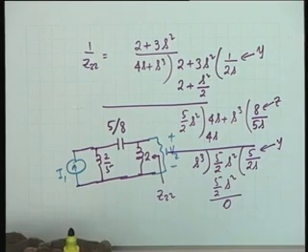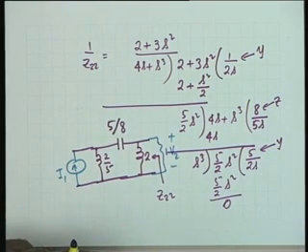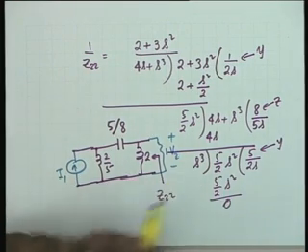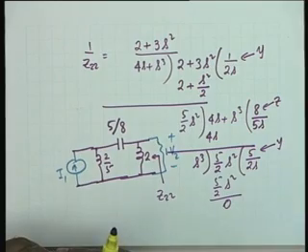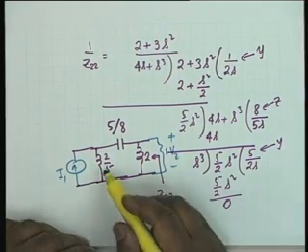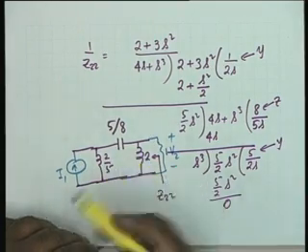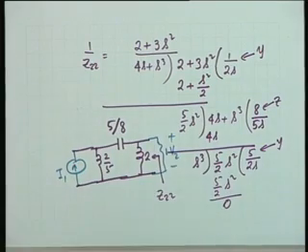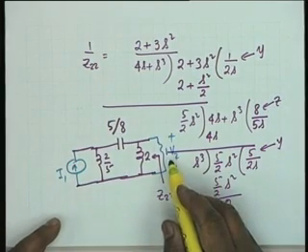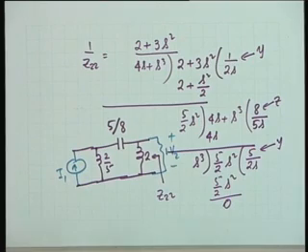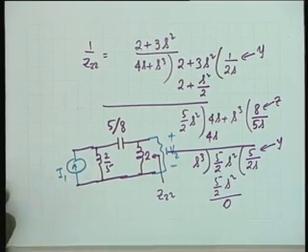What is the infinite frequency response of this network? Common sense, look at the network and it's a 1. Infinite frequency, this is open, this is open, this is open, this is short, so the total current goes, and since it is 1 ohm, so V2 is equal to I1, alright, so it is 1. So if we had started with Y21, would we have gotten a different circuit? You would have got a different circuit surely.